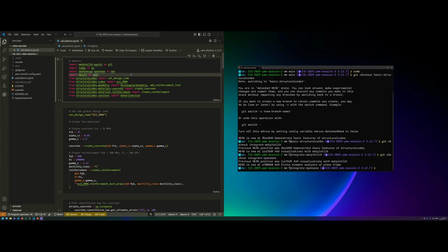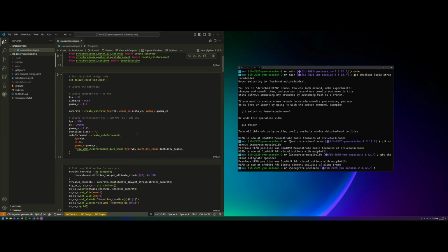So still all from inside the notebook, we are now importing these two libraries. We're importing openseespy.opensees as ops, and we're importing opsvis, which is the visualization tool, as opsv. So from these two namespaces, we will have available to us different methods that we will use to invoke OpenSees in the background.